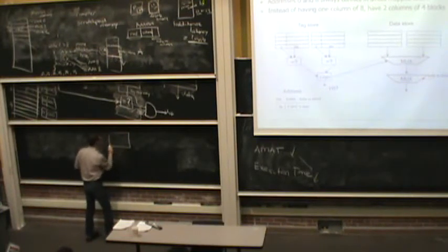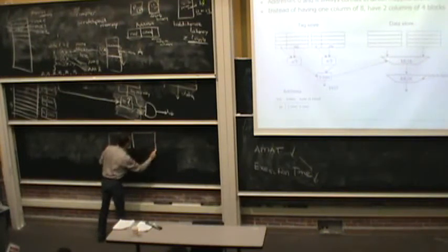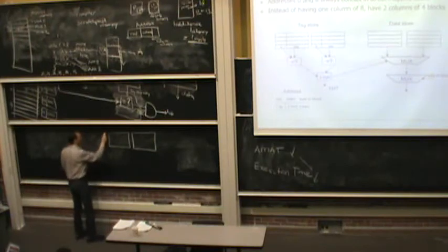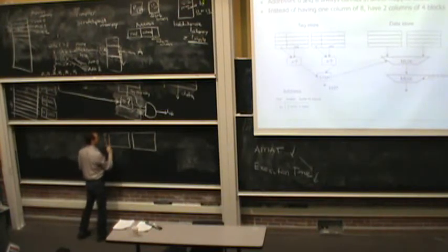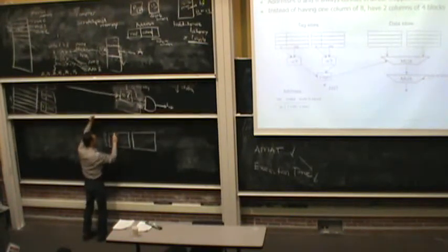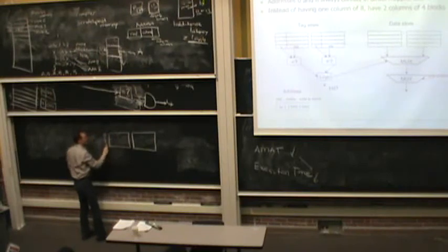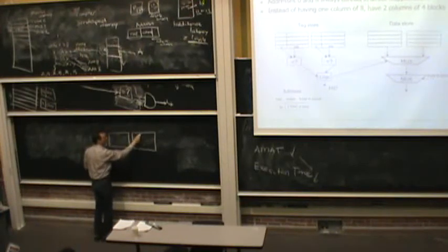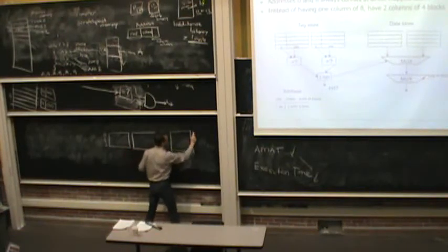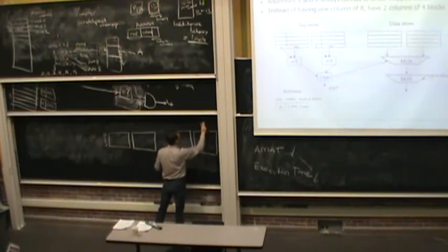Now, for each index, we can have the ability to store 2 different blocks, if you will. But we have a fewer number of indices in the cache. So instead of that single column of 8 indices, we have 2 columns of 4 indices, but these could store independent things. So we've divided our tag store and the data store.